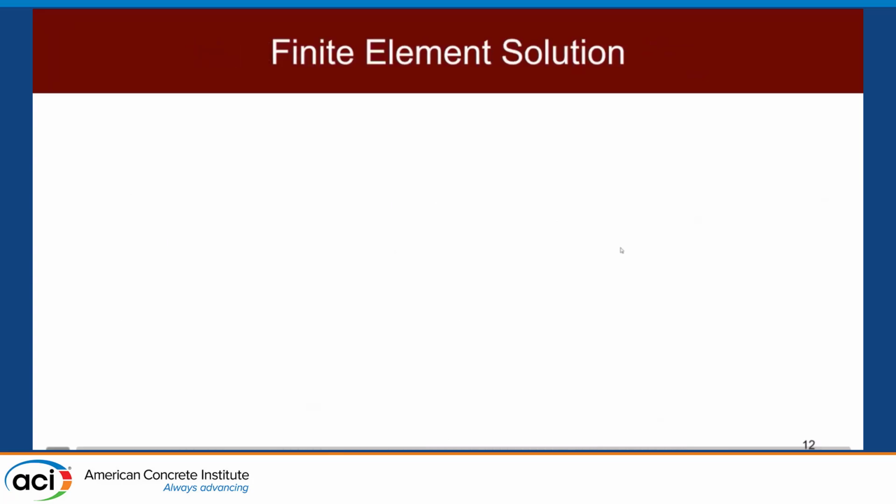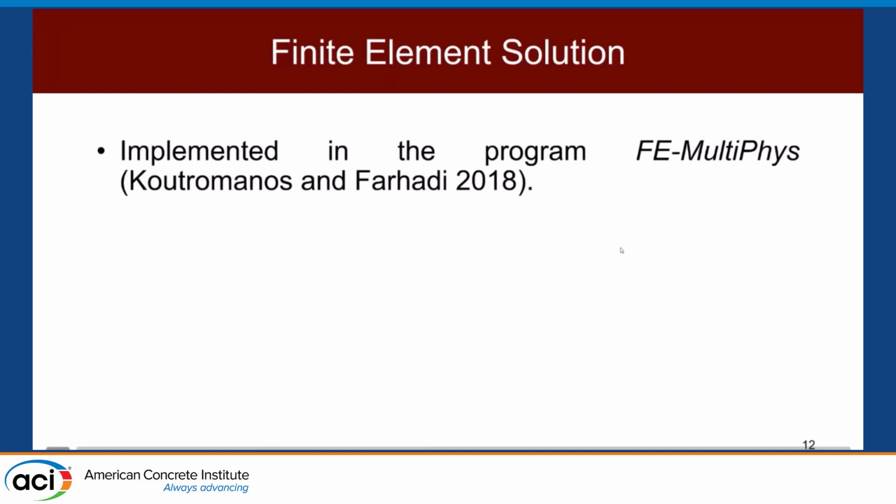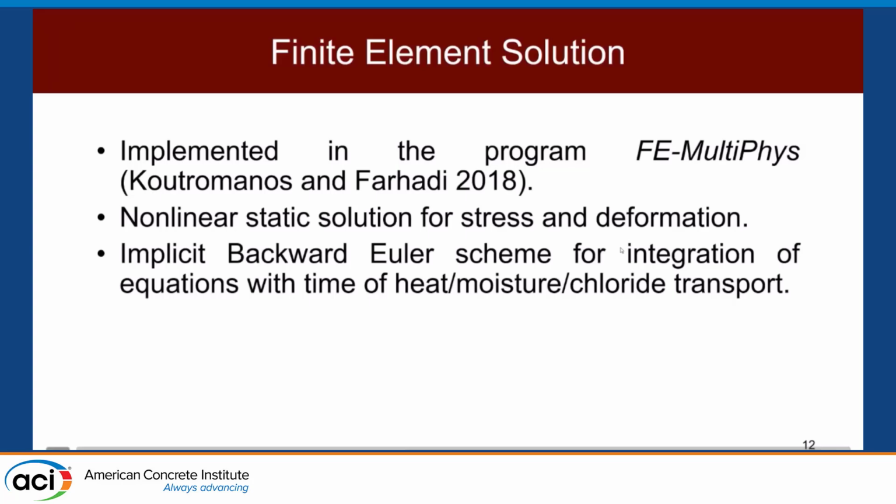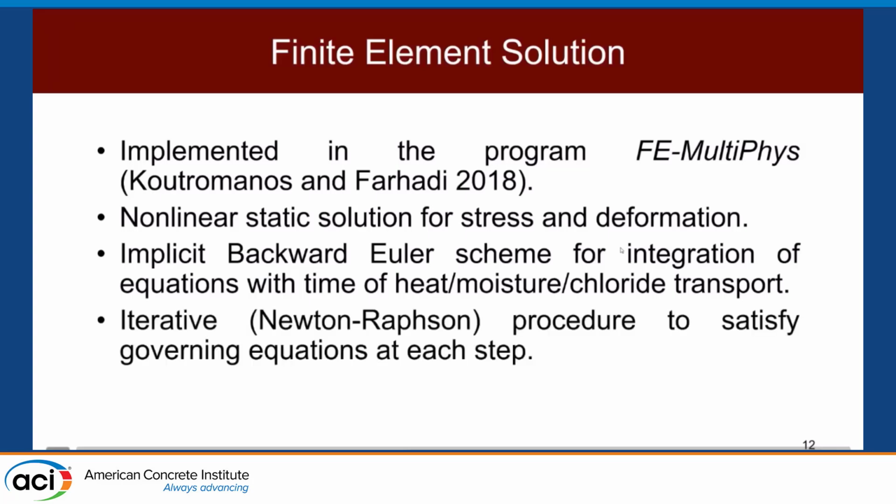Koutromanos. Now, the finite element implementation and solution of this mathematical model is implemented in our in-house research code, FE Multiphys. We employ a nonlinear static solution for the stress and deformation part of the computation, an implicit backward Euler scheme for the integration with time of the equations governing heat, moisture, and chloride transport.